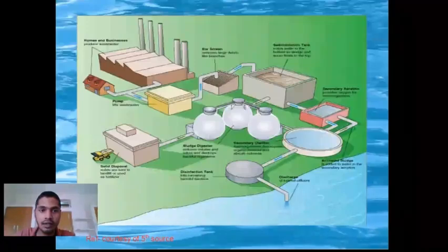So, effluents are the water runoff from domestic or industrial units. Based on the industry we are talking about and the domestic source, the composition of effluent can differ. The effluent from a house, for example grey water, tends to have high BOD, whereas in industrial units you may have high COD concentration. Irrespective of the effluent, they have to undergo treatment so as to reduce the BOD and COD. Now, why do we have to reduce the BOD or COD?